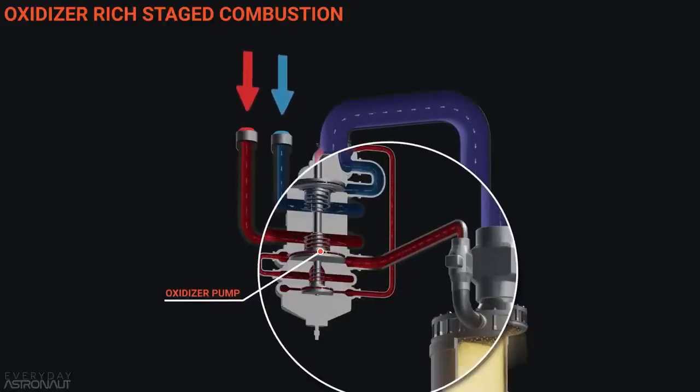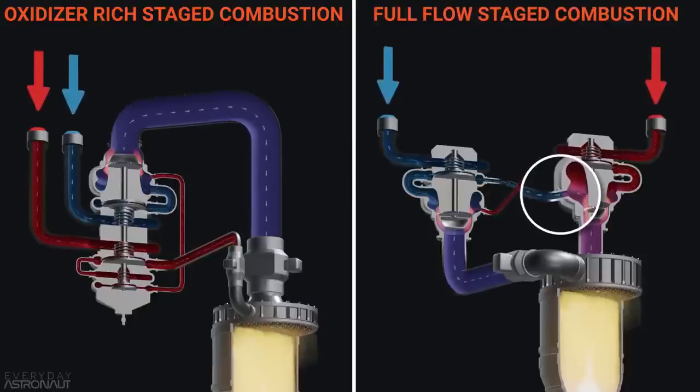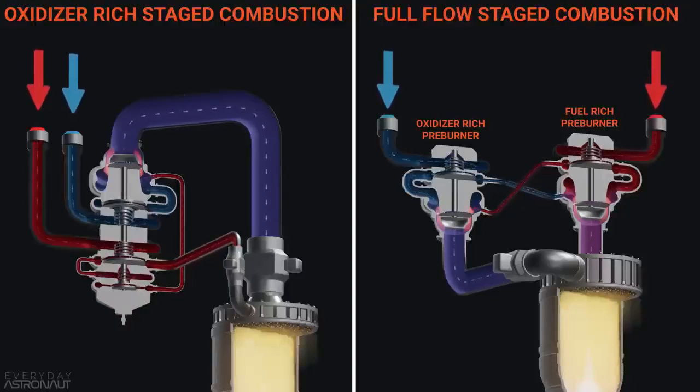What if we basically added just a dash of oxidizer to that stream of fuel and added another preburner to help power the pumps? It could share the load and decrease the amount of work the other preburner would have to do. The two preburners would basically be splitting the work needed to run the pumps. The less work the turbines need to do means less heat and pressure necessary inside the preburner to do the same amount of mechanical work.